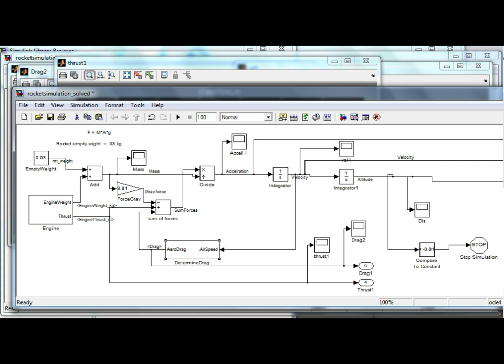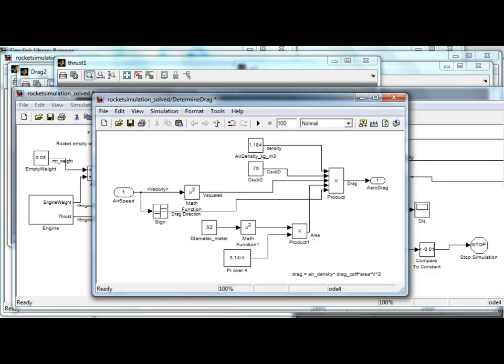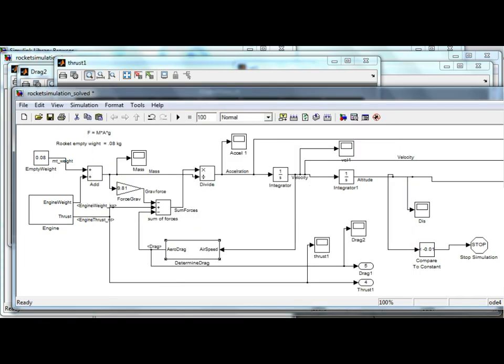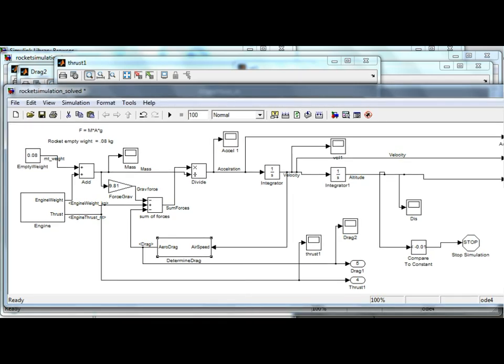But having these labels on everything, I can match the label on the signal with the label on the subsystem block. Going back into airspeed here, I have airspeed as my signal name. I have velocity as the auto-propagated name, and that just gives me a little more confidence that I didn't make a mistake. It's one more way to double check the results. If I'm looking at a model and I see a mismatch between the label on a port and the label on the signal, oh, I found a bug, and it's very easy, and it really pays off.